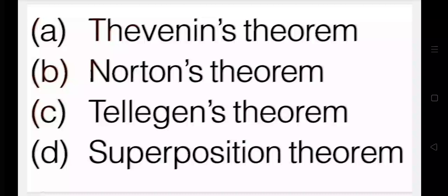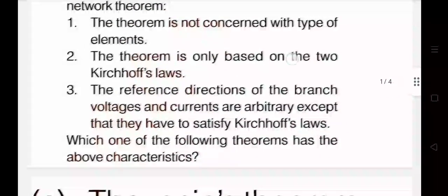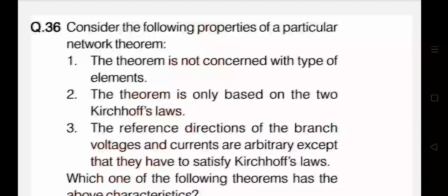Again, I will tell you what Tellegen's theorem is. Actually, Tellegen's theorem is applicable to any elements, that means whether they are linear or non-linear, passive or active, hysteretic or non-hysteretic. Tellegen's theorem is applicable for all these elements with all these characteristics. Again, it says that the summation of instantaneous power is equal to 0. This is what Tellegen's theorem says.